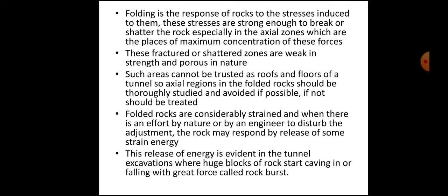Folded rocks are considerably strained, and when there is an effort by nature or by an engineer to disturb the adjustment, the rock may respond by release of some strain energy. This release of energy is evident in tunnel excavations where huge blocks of rock start caving in and falling with great force, called rock burst.